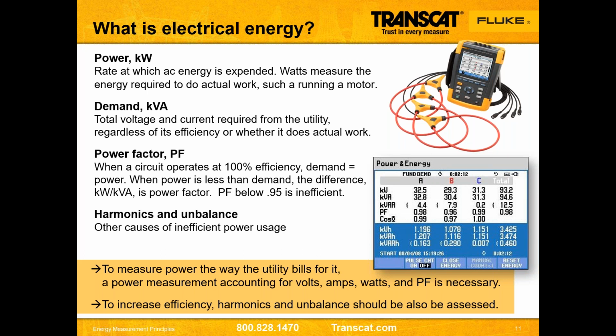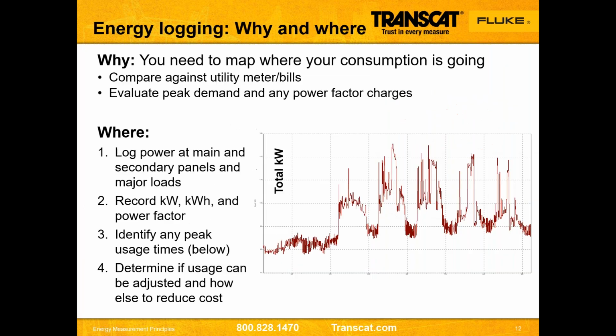So these are two issues within an electrical system, harmonics being a form of electrical noise or waste, and unbalance where my voltages on all three phases and/or my currents on all three phases are not balanced, they're not equal. It can cause inefficient use of power and cause waste. So we want to have the ability to go out and measure those devices, and the tool sitting up in the top right-hand corner is an example of a three-phase power analyzer called the 435. We have a wide array of these that can do this stuff and give me these answers.